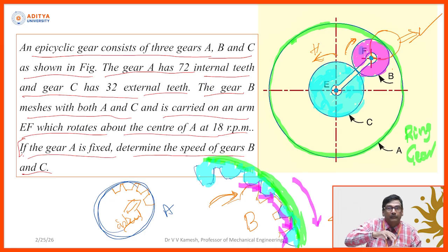By applying some force on the internal teeth of gear A, B will drive the internal teeth of A to move clockwise. Got the point? So, B is rotating clockwise and it will induce the internal teeth of gear A to rotate the annular gear, or the ring gear, also in the clockwise direction. The same thing will happen in anti-clockwise. So, the directions of B and A will be the same. This is regarding how the energy will be transferred.